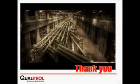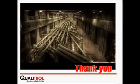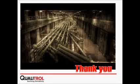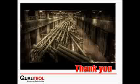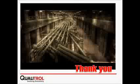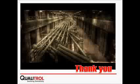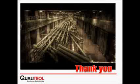But if you are ordering a new transformer, we highly recommend that you specify built-in sensors. You may choose later on to have continuous monitoring or not, but it's relatively inexpensive to order a new transformer with a built-in sensor, and there are multiple options available for all kinds of price ranges. Then you can use those sensors with either a portable unit or continuous online monitoring, as per your desire in future.